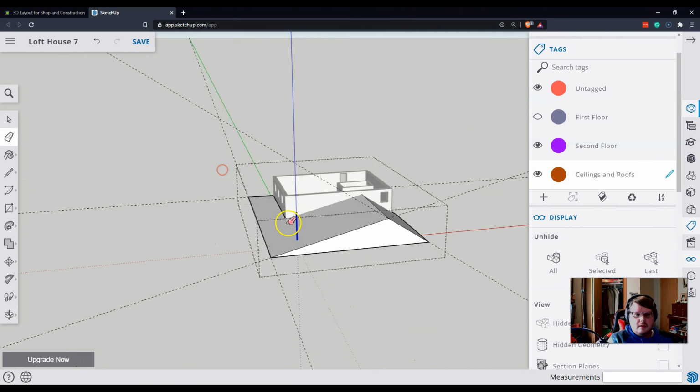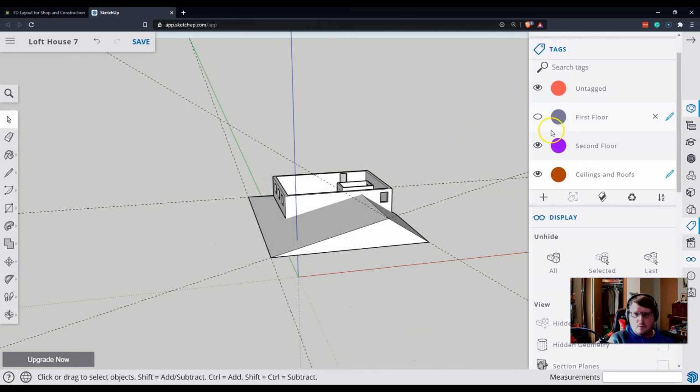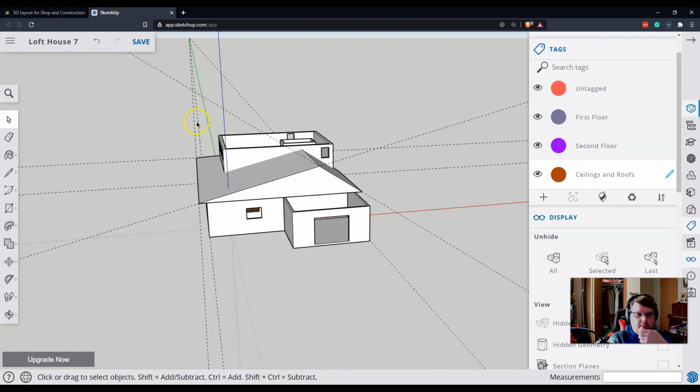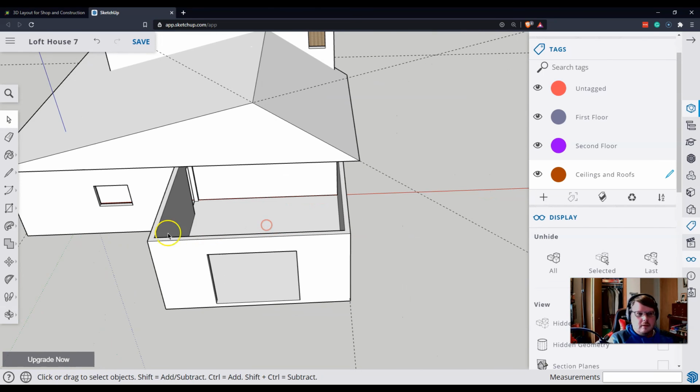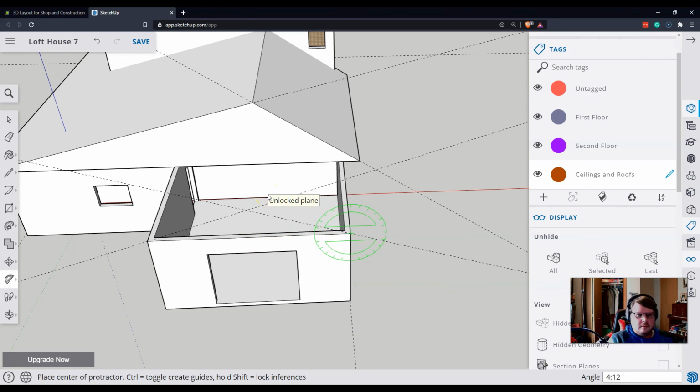There's our roof line. I'm going to just walk you through one more part, and then I'll leave you to do the top part, because I think the top part of the roof is fairly straightforward. It's just drawing this profile here. It's the same process as doing the other one. You just use this, pull it out till you get that. This is a 4:12 pitch. You do the same thing over here till it's green. And then here, and 4:12.